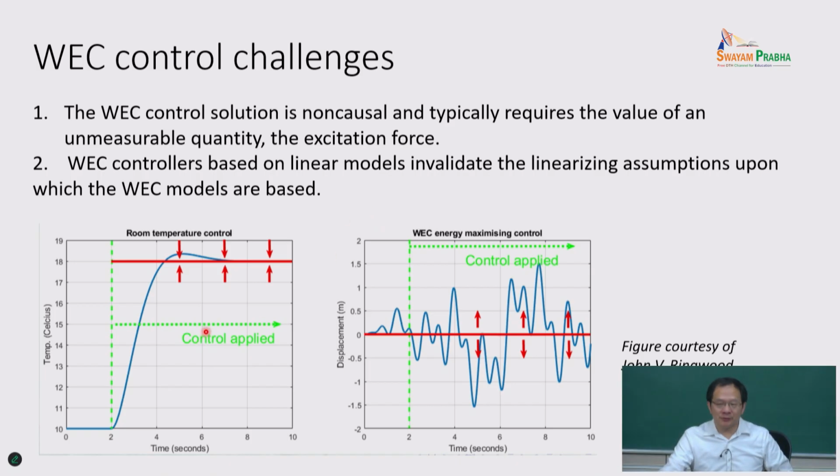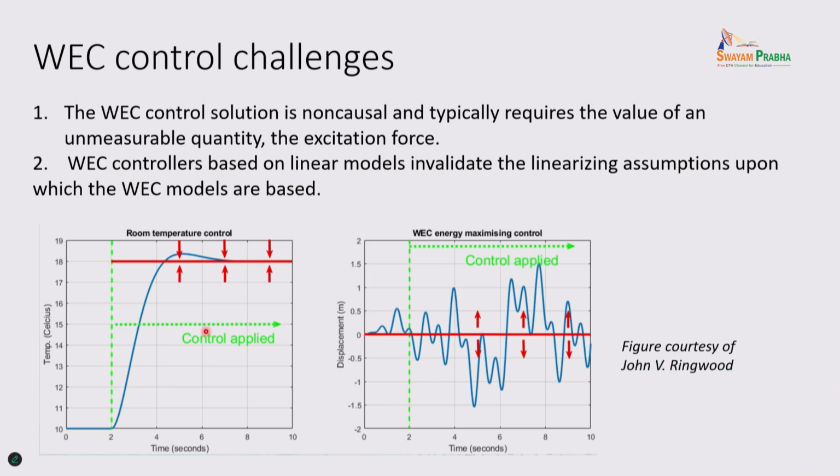Almost all vibration systems, no matter what, you want to reduce the vibration, right? Here, in wave energy, when you control that, you want to increase the motion, so that you get more power, right? Instead of reducing the motion. Or the hydrodynamics part, we said, okay, linear wave theory is so beautiful, right? Linear wave theory assumes small amplitude, right? And here, a lot of things are not that small, right? So anyway, that gives you a sense when you implement the control, the wave amplitude increases, right? And it is different from a typical control system, right?